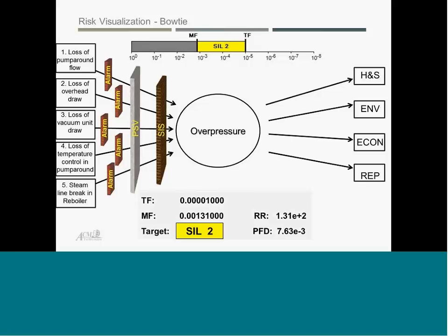So if you look at the LOPA graph, in this case, our risk is not changing as I'm going between multiple alarms and a single alarm. So what we get right there is a benefit of having fewer safeguards, which means less operational difficulties, less capital costs, and less time spent doing maintenance. Next question there is, are we safe yet? And the answer is no. Our mitigated frequency has not met our tolerable frequency, and we're still seeing a risk gap within that LOPA graph.